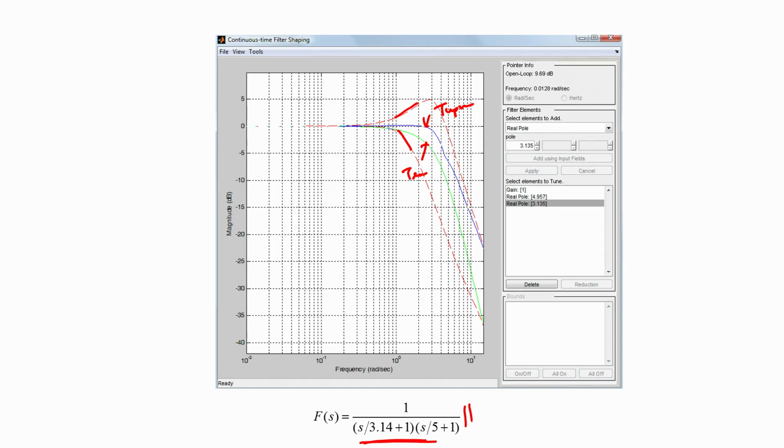So since the spread delta of j omega between T upper and T lower is significantly less than what we were permitted, our design in this case has been a little conservative, or in other words, as a consequence of this particular controller and this pre-filter, we are permitting our closed loop pole to wander in a region that is smaller in area compared to what it could actually vary within, namely the rectangle that we had specified at the start of the design procedure.